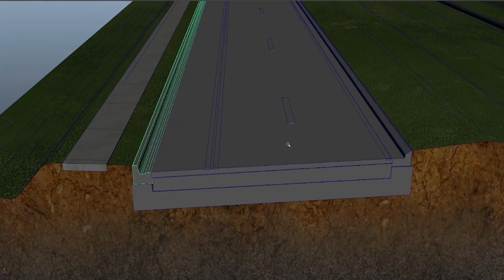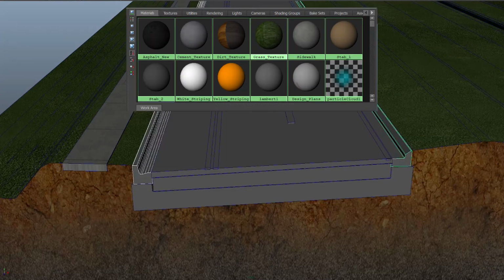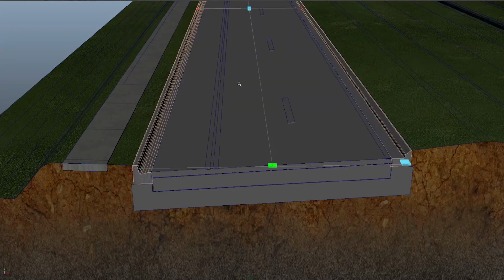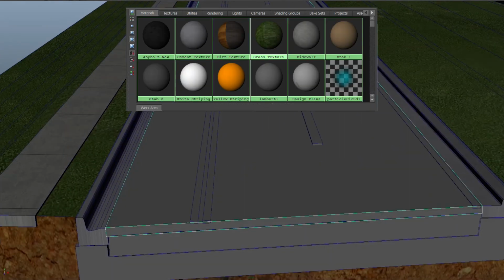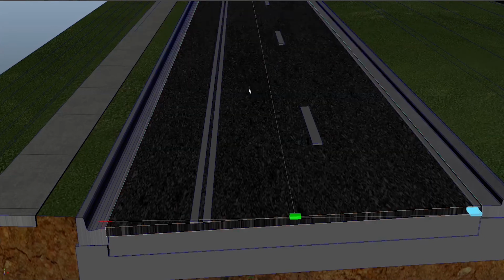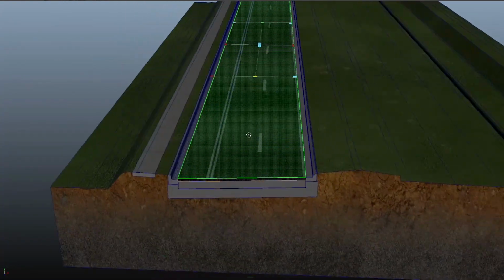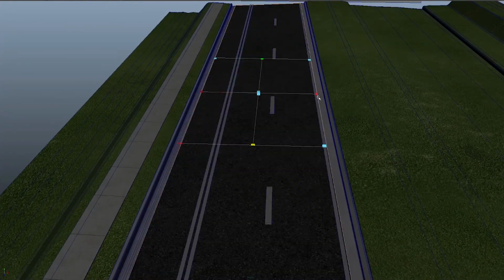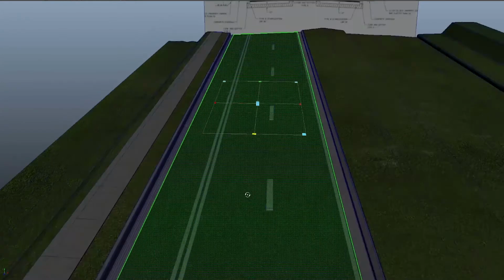Now let's do the curb and gutter. Same process. Go to your textures menu, add your cement texture, do a planar map, tile it, done. Now for the road, we'll add an asphalt texture, and we want to go straight down, planar map from Y again. So then you see this nice asphalt texture there that's already set up, and it's tileable, so you can repeat and scale this however you like. But again, we don't want to make it too repetitive, otherwise it's really easy to spot.